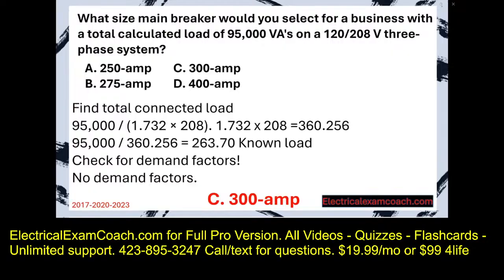meaning that we'd have to have larger wire in the previous question, which may lead us to have larger pipe, which we may end up with a larger cost of overall project. The beauty of three-phase is the numbers come down. So this one's on a 300 amp service, which means we can put it on smaller wire, which might mean we can put it in smaller pipe, which might end up having a smaller overall cost.